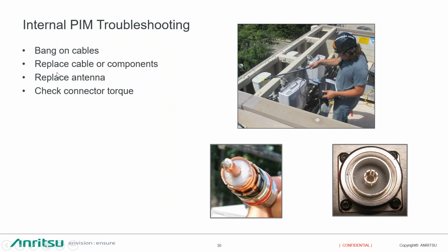I do think operators have a pretty good handle on quality control on their antennas and components. So normally it might be just a bad connection or corrosion that's happened versus a bad component, but you never know. Sometimes poorly tested components that may not be properly PIM rated enter the network somehow. Checking your torque on all of your connections.